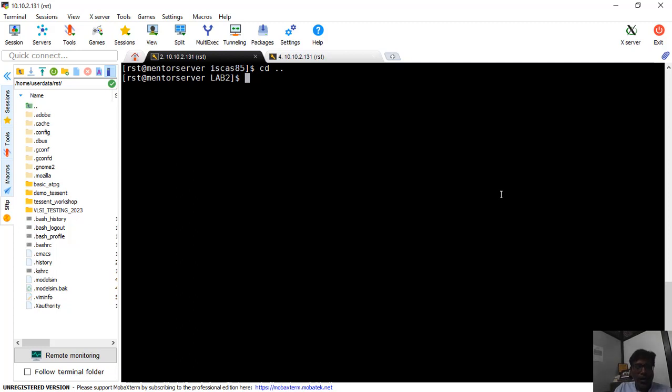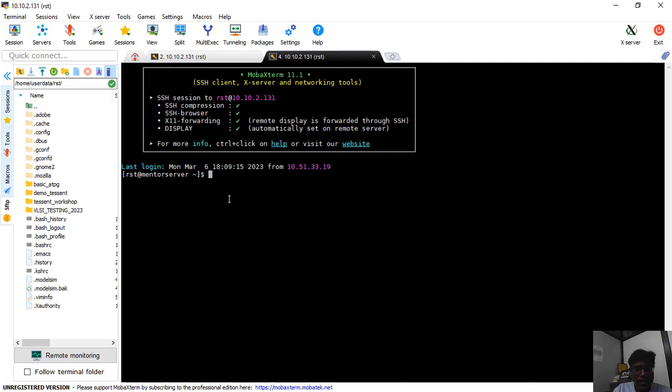So I am here. So how do we access the tools? See, first you need to change the shell. So first give the command csh, then source your .cshrc file. This is more important. So these are the two commands which you need to give. The .cshrc file, as I said earlier, consists of 4 commands. I will also open that and show you. If you want, I can open that .cshrc also.